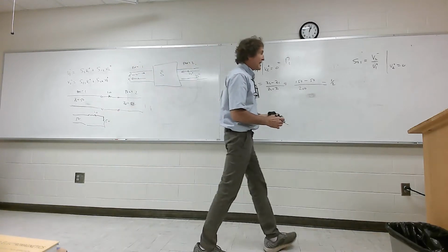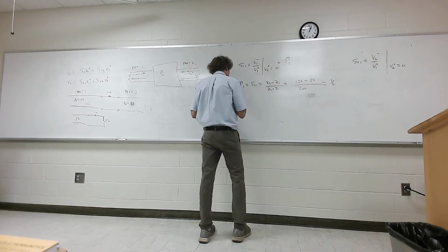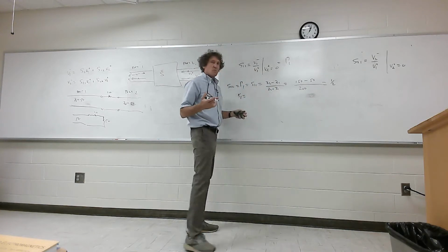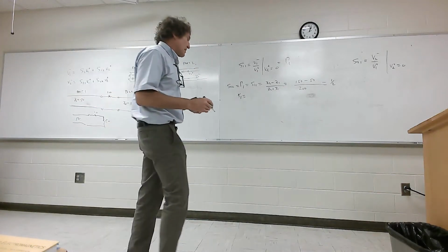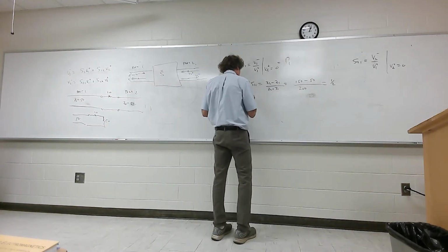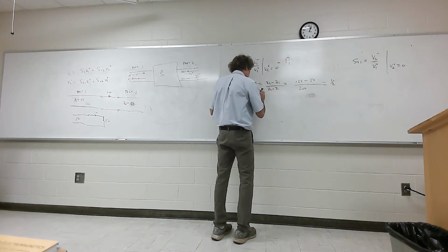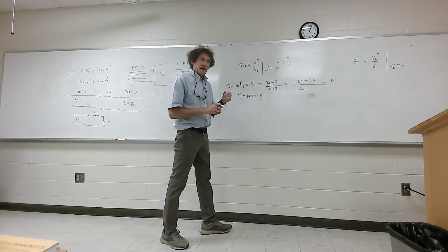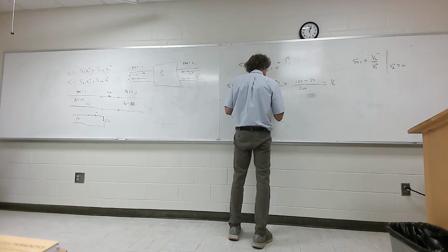So over here, the way I get it, first I need to get the transmission coefficient, port 1. And one way to get that is what? 1 plus the reflection coefficient is the transmission. You can do it that way. It would be 1 plus 1/2, which is 3/2, right? Well, put it as 1.5. You can also get it by saying it's 2 times the impedance you're going into, 2 times Z2 over Z1 plus Z2.